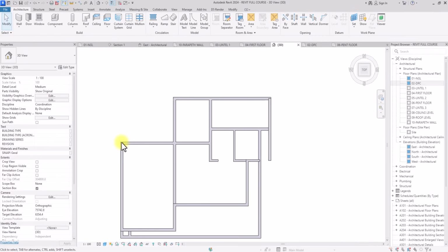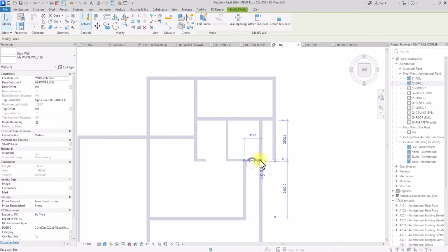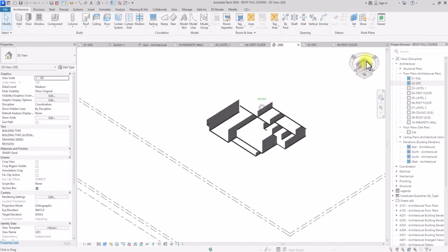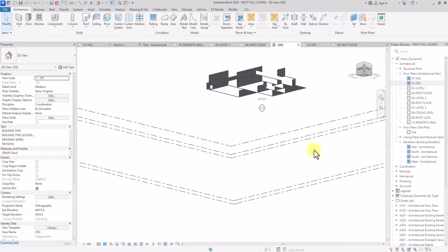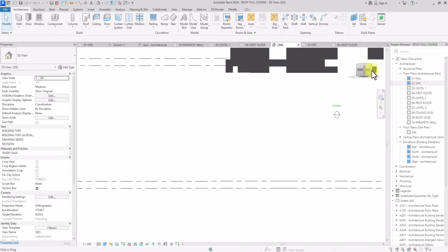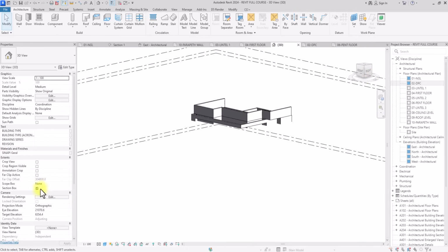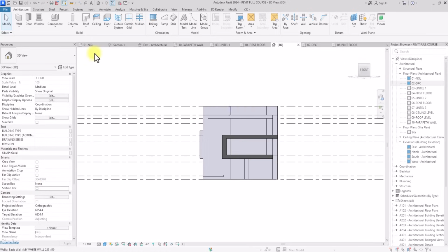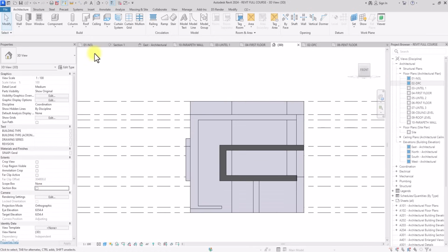So as you can see now, these are the parapet walls. I'm just going to extend this to here, so we can now see what we've created on the parapet wall. Currently, we'll have to turn off this section box to see our whole project. These are the parapet walls, but I want to create some variations within this parapet wall, and I want this center parapet wall to be higher than the others.